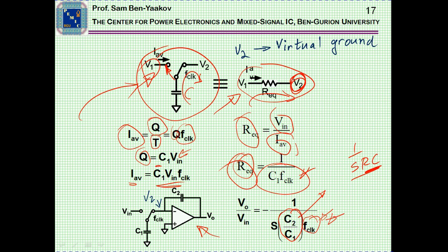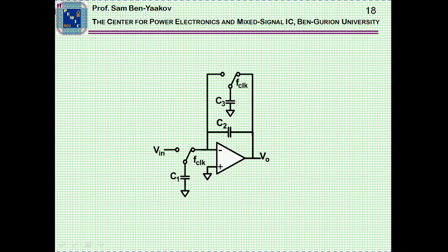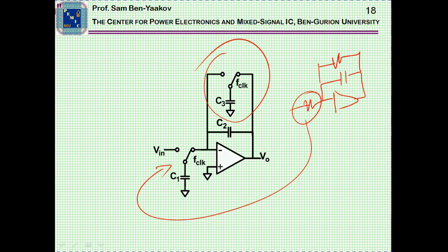You put the capacitor usually at the output, and you can then program it to emulate any given number of filters of low pass, band reject, or band pass. Of course, you can put this switch capacitor in the feedback, and then you'll get a simple low pass filter like this, because this is now this switched capacitor, and this is this switched capacitor.